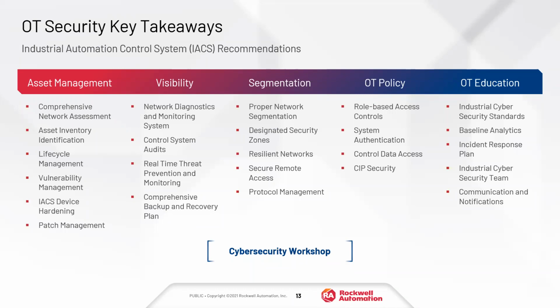We have documentation, as I mentioned, that would help you understand some of your security options, whether you're starting the conversation or whether you're trying to validate the changes that you're currently making in your system. As I mentioned, an example of this is the ability to change the external access of tags inside of a controller. Do you want someone to be able to read write, read only, making it what's called the constant? Those are all available within ControlLogix, CompactLogix.